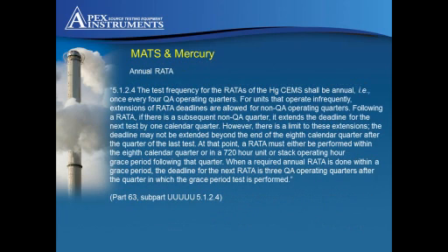So right now, I have on the screen text from Part 63 that addresses the frequency in which the RATAs must be performed. A basic summary of this section is that the annual RATA must be performed within the fourth operating quarter of the yearly anniversary in which the sorbent trap monitor was initially certified. It is assumed that you can perform the RATA anytime within that 4th quarter.